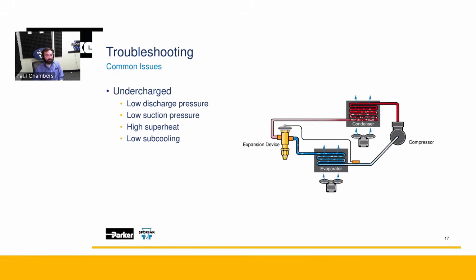I'm going to have low subcooling. That's the 4th point there. Because if I can't hit that high pressure, I can't squish all my refrigerant together. I can't force it to condense into a liquid in the same way. So actually, I'm going to have a lower subcooling number. I'm not going to get as far outside of that pressure enthalpy dome that we saw earlier.